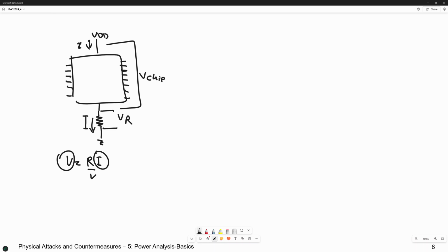Now, these attacks are called power analysis attacks. We are not measuring power, we are actually measuring the current. We do not want to get something in joule or watt or anything related to power or energy, nothing at all, just something proportional. Now we measure the voltage using an oscilloscope, as we will see later. And for the current which is passing through this, we will have something relevant to it.